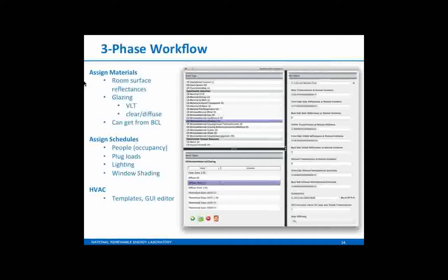So you can specify a piece of diffuse glass, which is more often than not the case in the case of the skylight, and that will actually properly translate over to Radiance. So it'll use a trans material in Radiance, if you're familiar with the different materials, instead of just glass, which is what it used to default to. So a little bit of extra capability there.